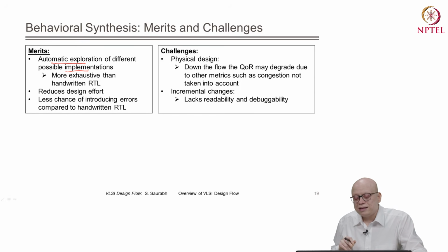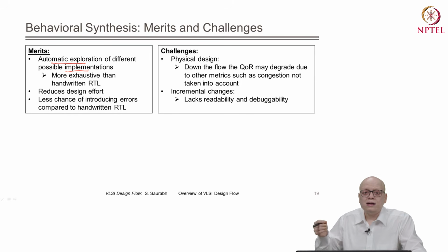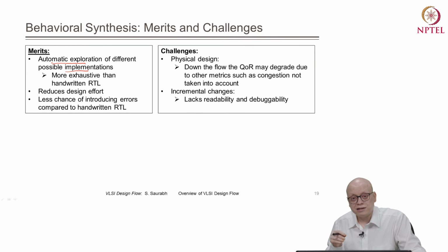The other is the lack of readability. The machine generated RTL code after behavior synthesis is not easy for a human to read and understand. So if we want to make incremental changes or do some debugging in the RTL generated by the behavior synthesis tool, it is really difficult. That is a big demerit. Another problem is that if we make small changes in the algorithmic behavior, the RTL can change widely.